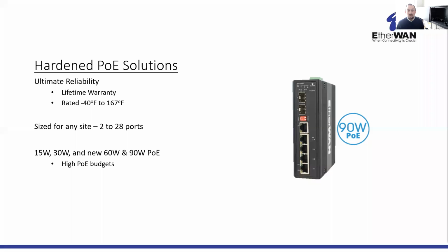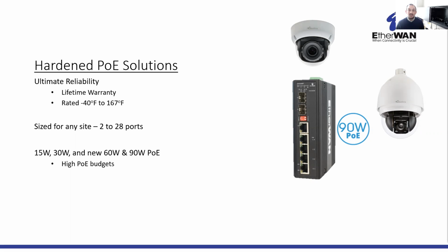So having that high PoE budget is going to be needed because you might have multiple cameras. That could be a standard fixed lens or varifocal camera. It might be a PTZ. There are a lot of PTZs already on the market that have been using a 60 watt standard with custom injectors while that was actually being worked out as a standard for true PoE from switches. So those 60 watt devices, you're going to be able to power off of this as well.